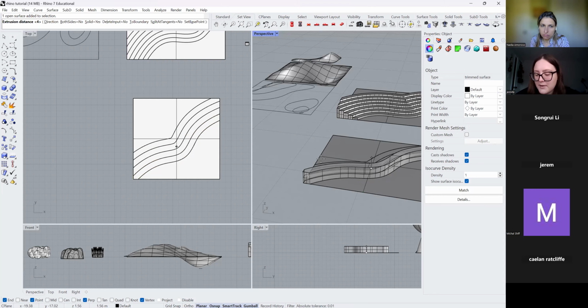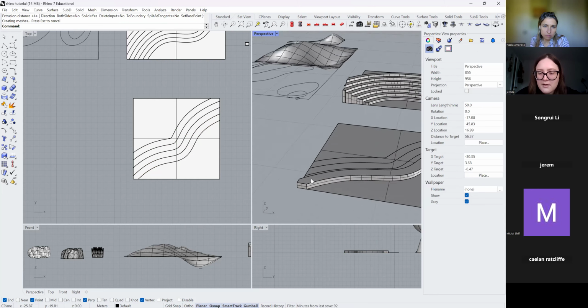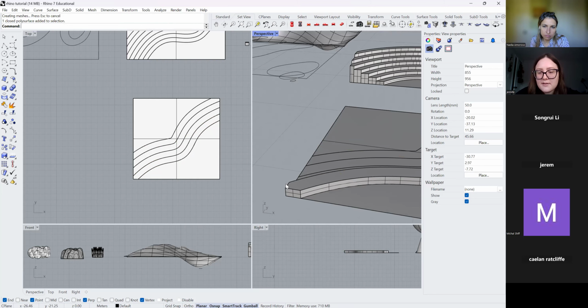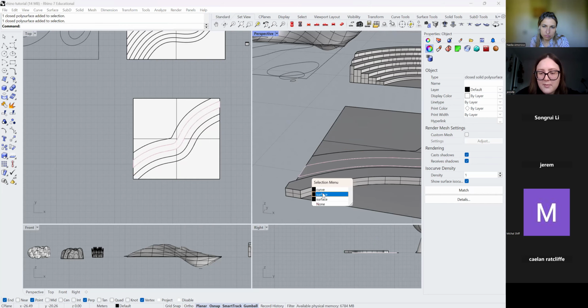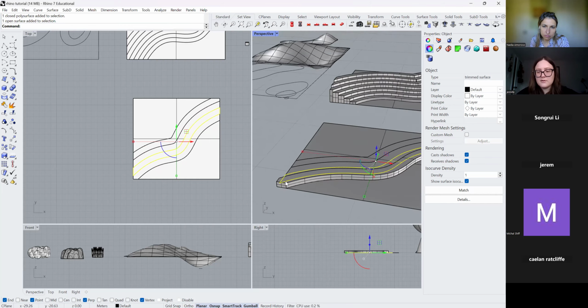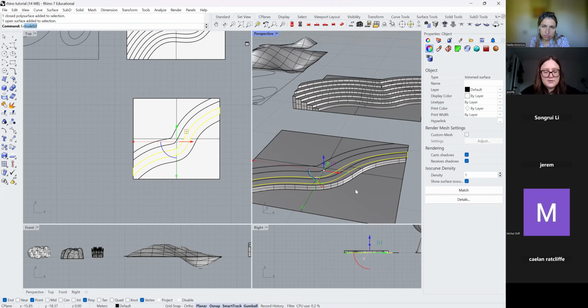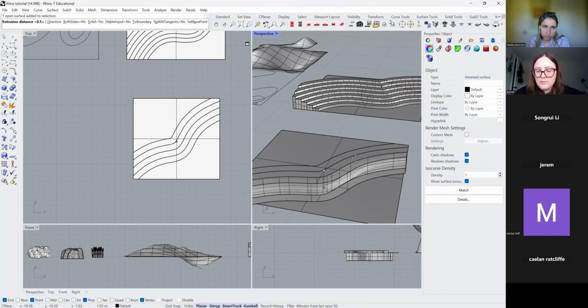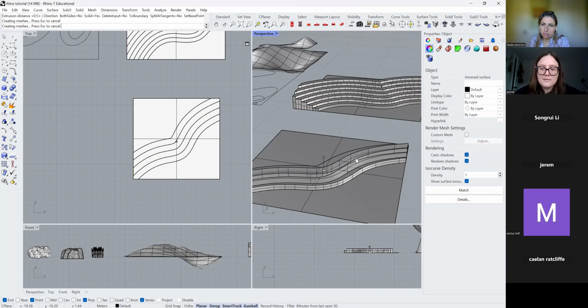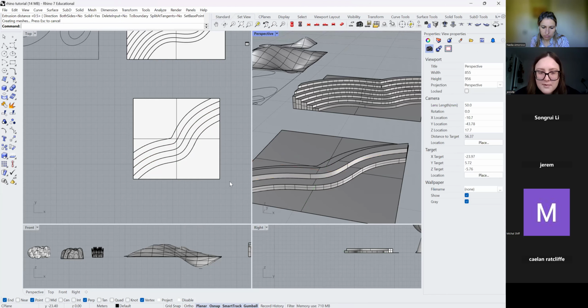And then I'm going to type in 0.5. Okay. And if it appears and it's not closed like this, you would click cap, but this one's closed. Okay, extrude, and this one would be 1 meter. Okay.